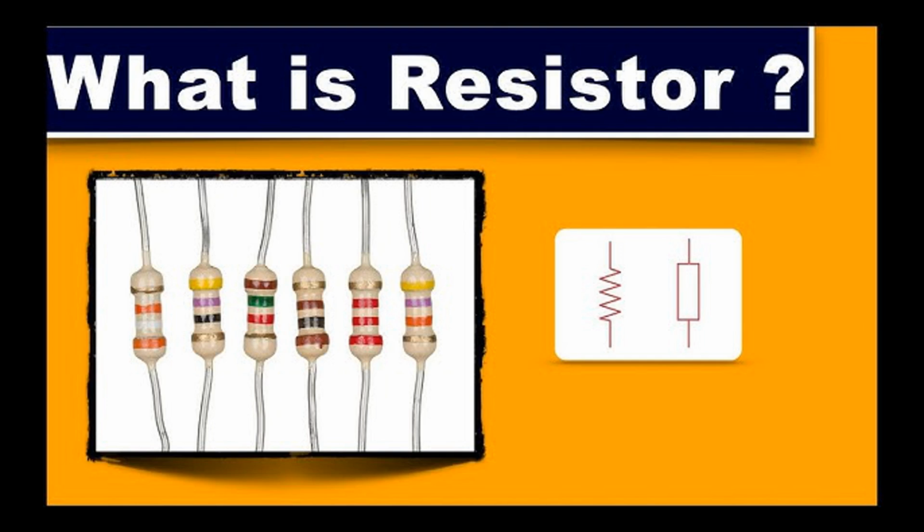Minimizing signal reflections. Purpose: in transmission lines, such as those used in RF and microwave circuits, impedance mismatches cause signal reflections. These reflections can lead to standing waves, signal loss, and distortion. Example: in a coaxial cable transmitting an RF signal, if the impedance of the cable does not match the impedance of the antenna, part of the signal will reflect back toward the source, reducing the efficiency of the system.